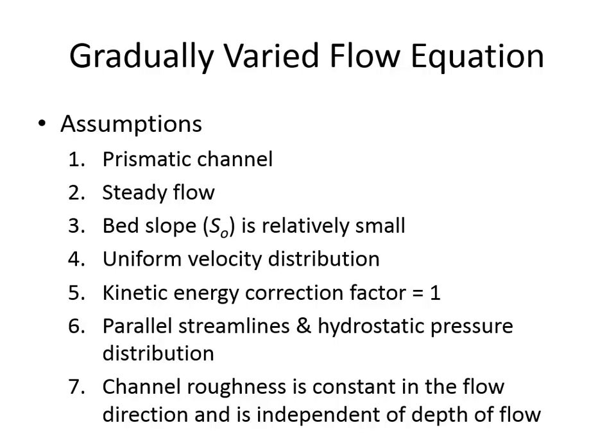Like I said, there are some assumptions we have to keep in mind as we apply the governing equation that we'll look at today. This governing equation assumes that the channel it's being applied to is prismatic. What we've defined a prismatic channel as before is one that has a regular geometry, that can be defined by shapes like triangles, rectangles, squares, not irregular, in other words. And so a non-prismatic channel would be a river bottom that looks like that.